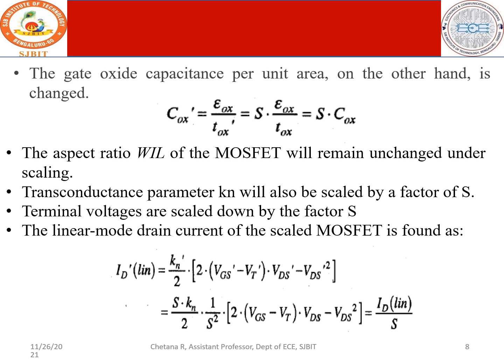When we are talking in terms of scaling, the scaling parameter associated with the original capacitance will give you another value called Cox dash. Since it is oxide, we have it as epsilon Ox divided by Tox dash.